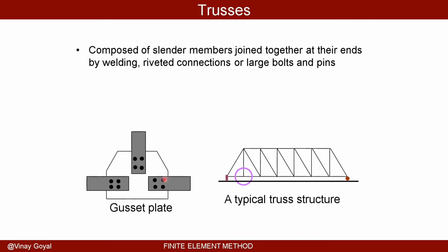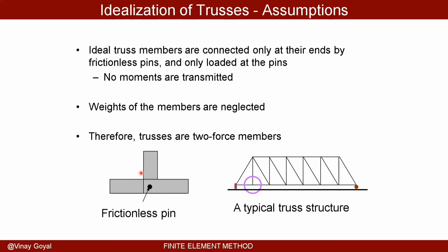Imagine if I model every single rivet and every single bolt in an aircraft application. That'll be very impractical. But instead, what we do, we try to understand the forces, the load paths, and then combine that with some hand calculations. So we want to be smart about that.